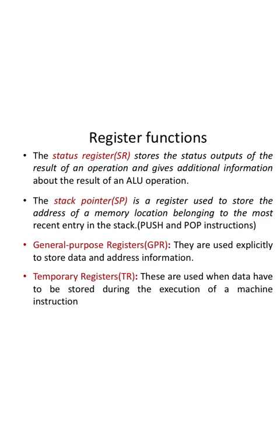The stack pointer is a register used to store the address of the memory location of the most recent entry in the stack, used by push and pop instructions. General purpose registers are used explicitly to store data and address information. Temporary registers are used when data has to be stored during the execution of a machine instruction.